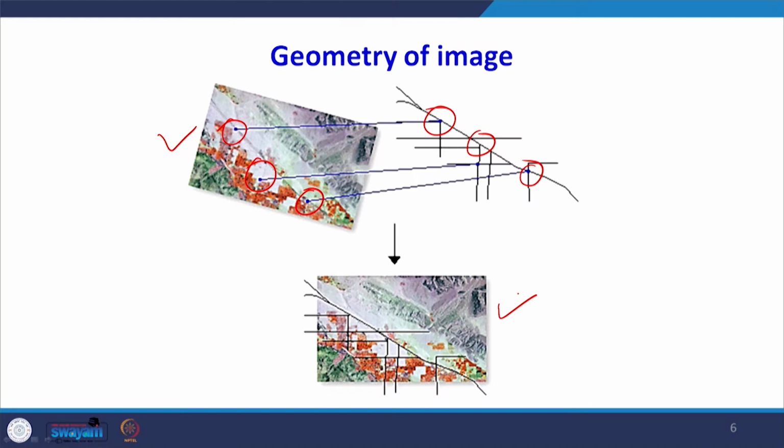For us, those latitude and longitude lines are very important, and north direction is important, because we have to orient the map in that direction so that we can match the detail. The figure below is the oriented figure with respect to earth, and now there is a one-to-one match as far as the details are concerned on the ground as well as on the satellite image.